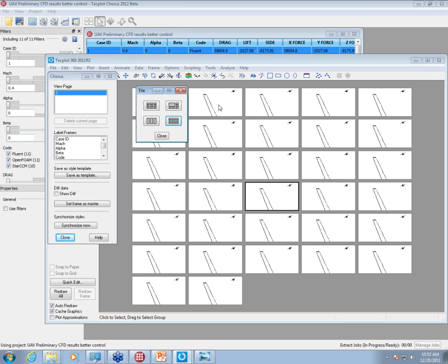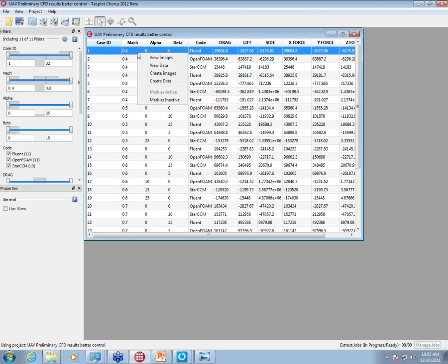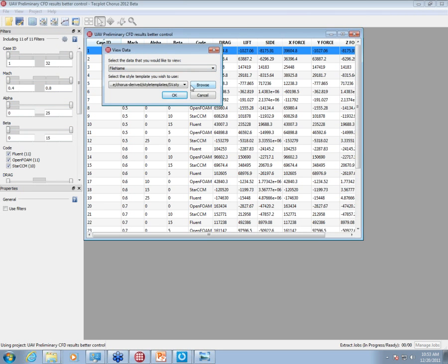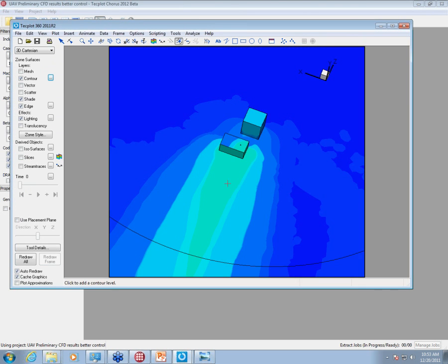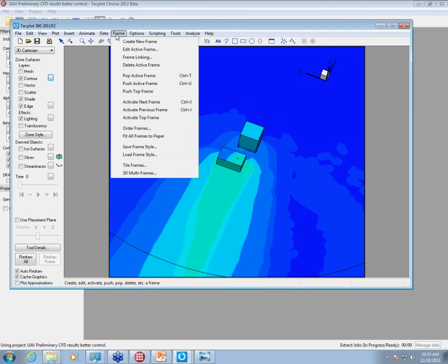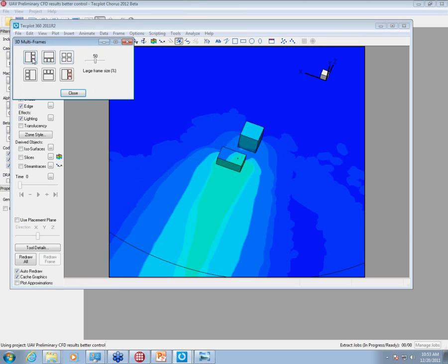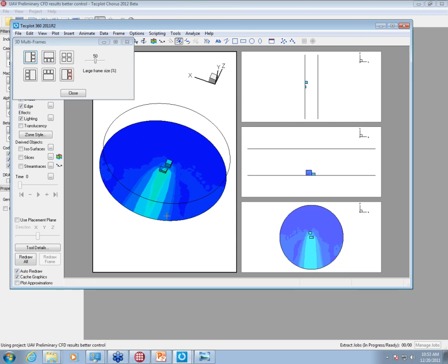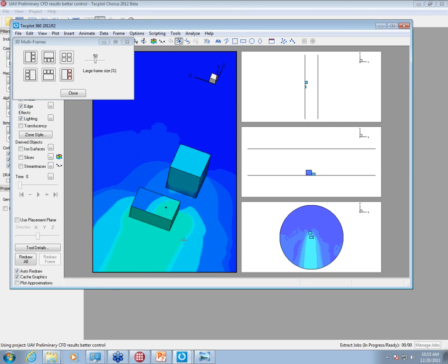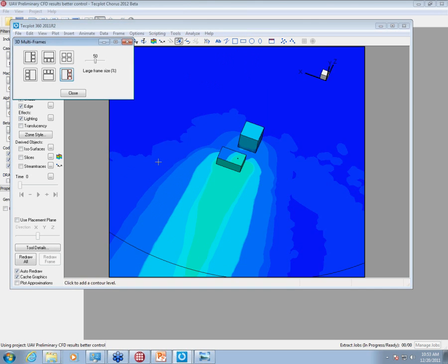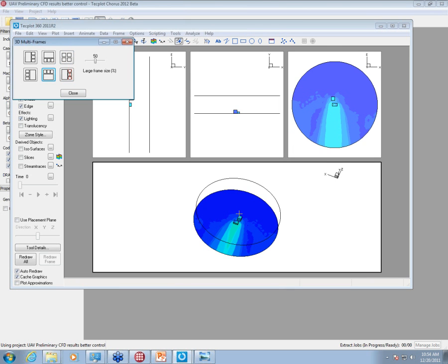The other thing that it allowed you to do, if we just go back to one result, and without a template. Okay, even on this one it's fine. The other thing that it added was the ability to do projected views. So now we're looking at the principal views, the XY, the YZ, and XZ. So traditional engineering plotting. It simplifies that process quite a bit, and you can go right back to your initial view. You can also play around with how it's done.